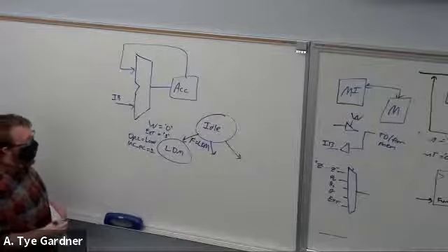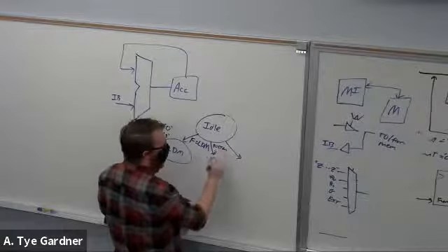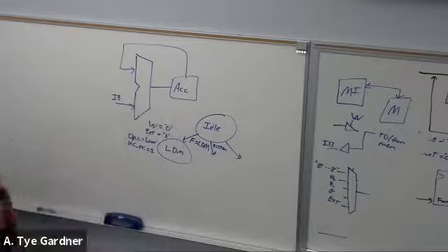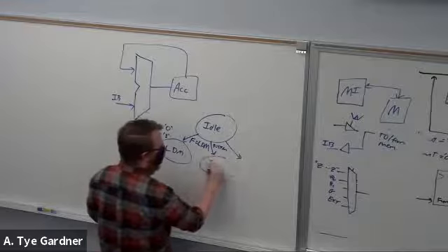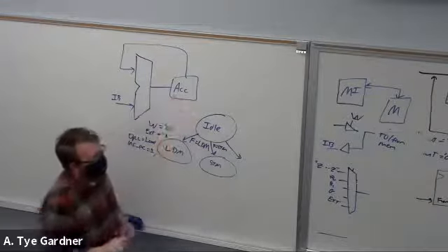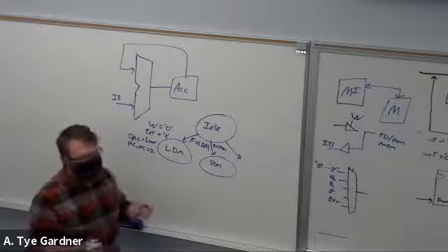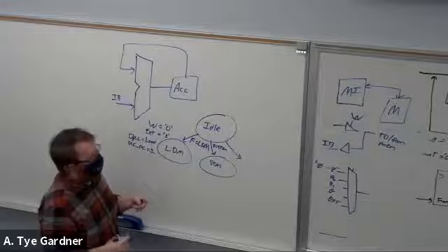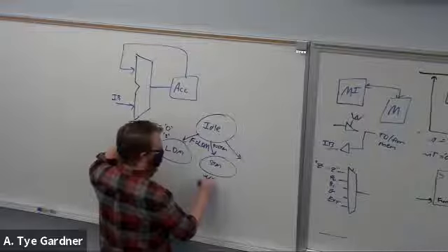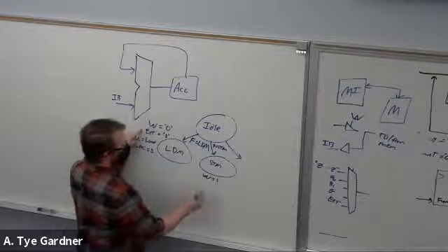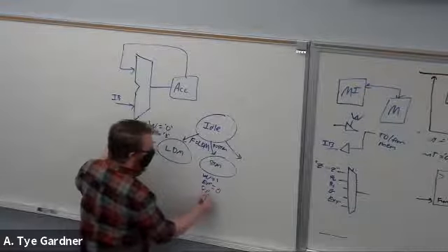Store to memory then, right? So if F equals STM, store to memory, then I have to think about what does that mean? Well, we go to the state STM. I have something in the accumulator. So I need to say, okay, well, on the first clock cycle, I'm going to assert write. Extern would be 0. Opcode is what?